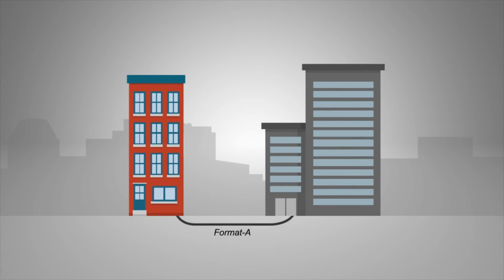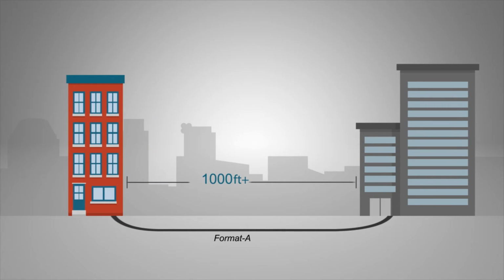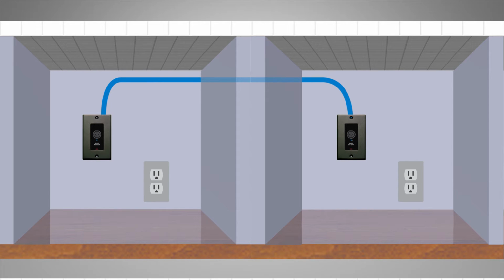Format A supports cable runs between senders and receivers up to several hundred meters with exceptional interference immunity. Senders and receivers are frequently mounted in walls where local power is impractical. Those senders or receivers can be powered through the twisted pair cable. DC power may be connected at one end to power the modules at both ends.